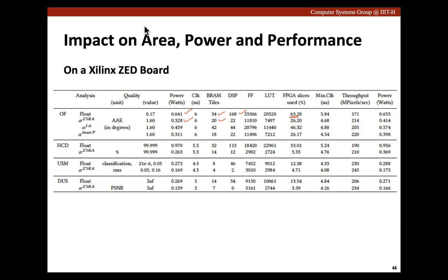So you should not immediately conclude that the other paper is better performing, because if you look into the details, the paper which is performing lower could be using a floating point data type, and the other paper could be using a fixed point data type. And while using a fixed point data type, it is not guaranteed that you'll always get the required accuracy. So that's what we should look for.